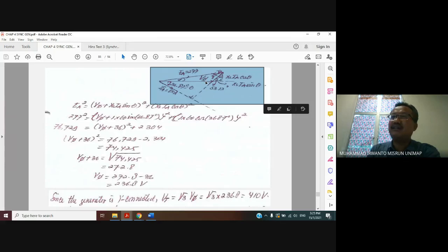And then after that we obtain the armature current, that is given from the question. IA is 60 ampere, but for the angle minus 36.87 degree, it is theta. Because IARA is ignored, so IARA and also JXSIA are part of the voltage drop.